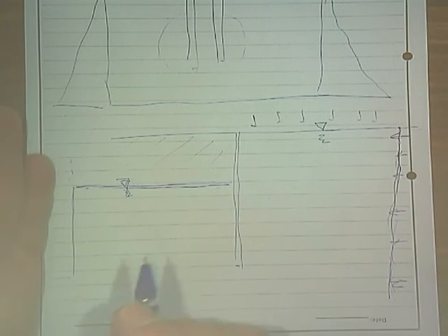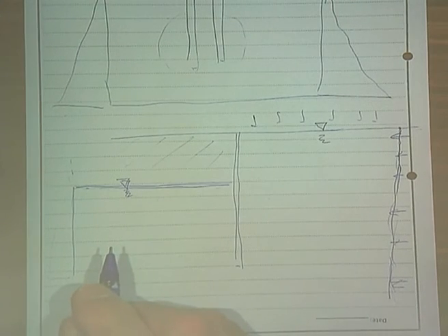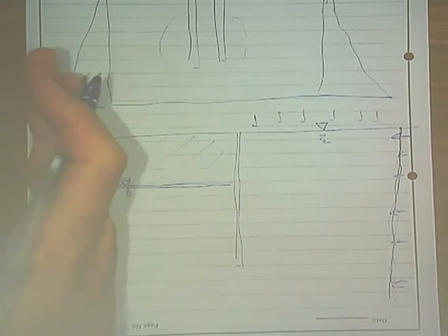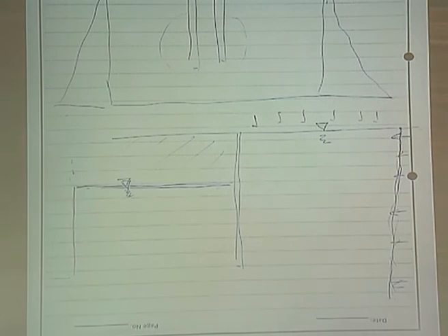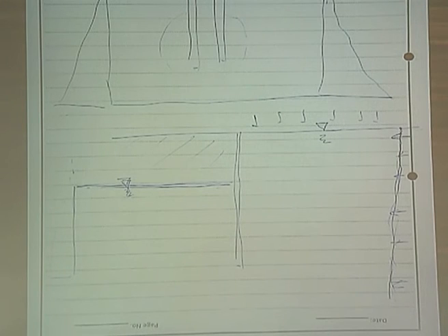It's just what we call a closed boundary. What Plaxis would call a closed boundary. So you close that boundary off. No flow will go through here because you're assuming that there is a mirror image of this excavation on the other side.